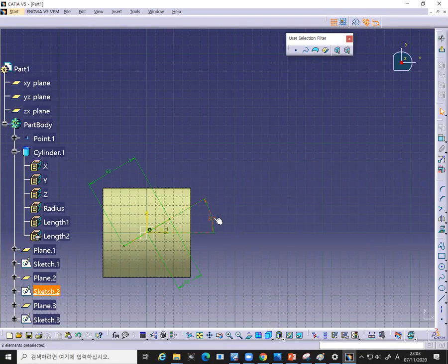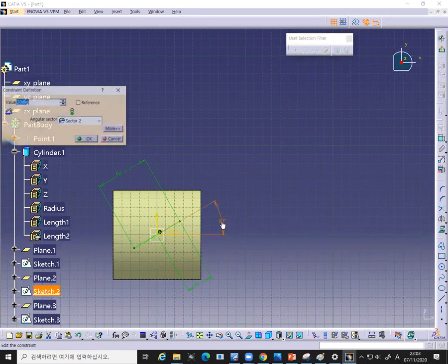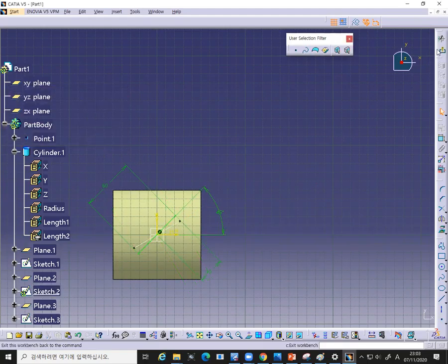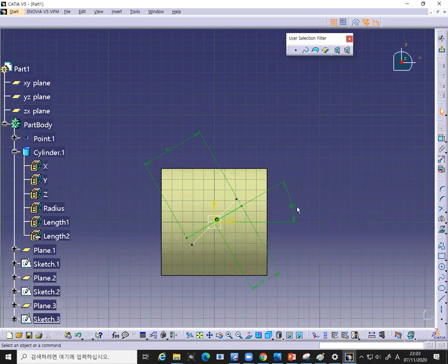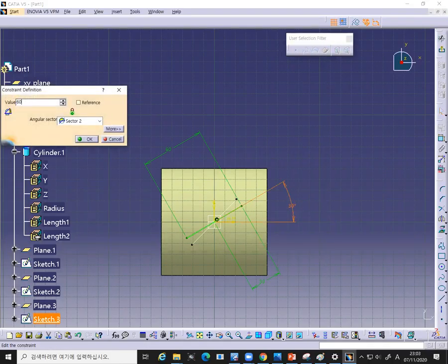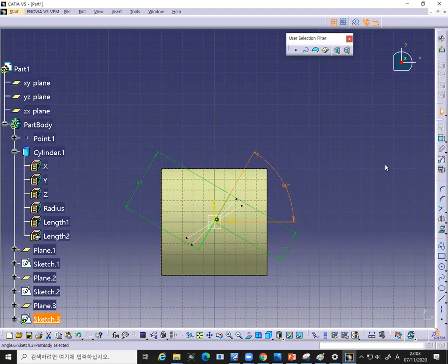So I click the mean sketch, right, at the mean. So that is a 45 degrees angle. And again, at the tip sketch, change. So we have to change this to 60. Okay. Yeah, so 3 different lines at the 3 different planes. So this is at the hub, this is at the mean, and this is at the tip radius. So angles are different, so change those angles.